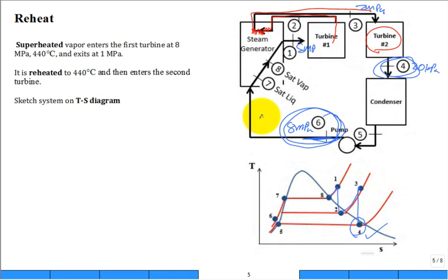It's about 60 degrees C, 61 degrees C. It's pretty cold. At 8 megapascal, it has to be heated up to state 7. That's just an intermediate state inside the boiler, where it's saturated liquid. Again, that's around 295 degrees C. So from 60 to 295, I'm bringing in a lot of energy, and it's at low temperature, not good for performance.